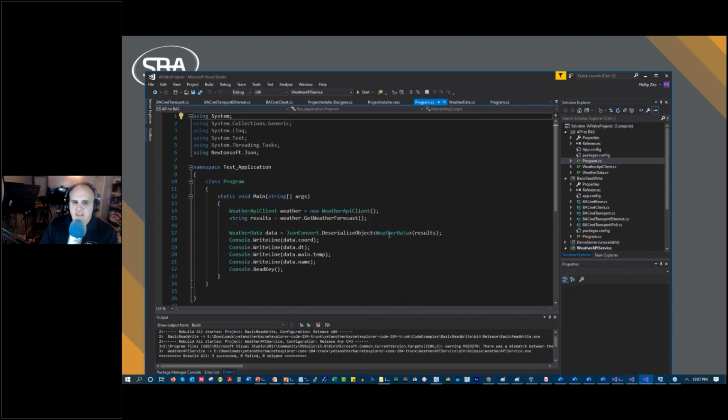I'm reading the data from the API, and then from that, I'm running a Windows server that writes the API data out as a basic BACnet server so that I can route it into a building automation system via BAS. This would run as a service on a server. Now, this is very much prototype code, but you're getting the idea of what a programmatic integration is.